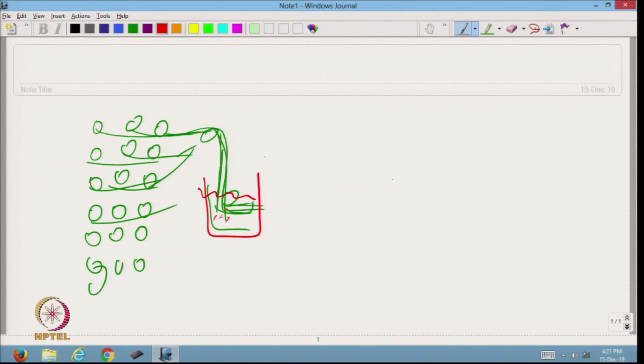The resins are here, and then this thick filament immersed with resin goes through one die. This is the die shape, and the filaments will be pulled through this die to form the required shape of composite.